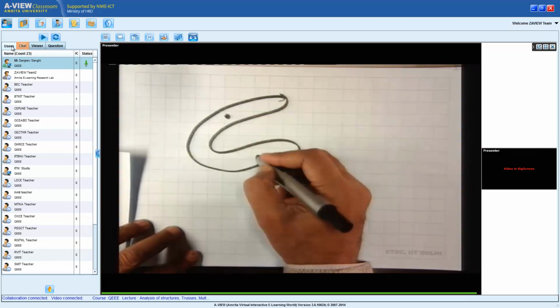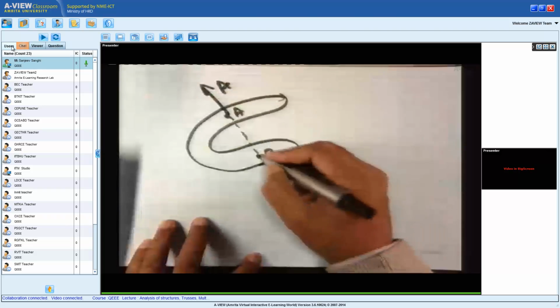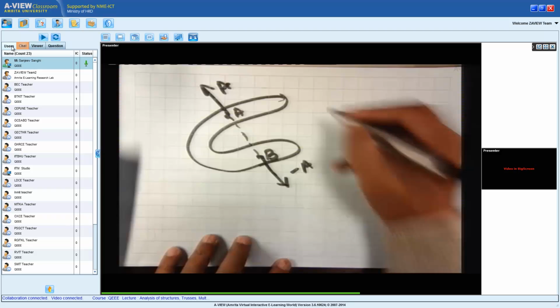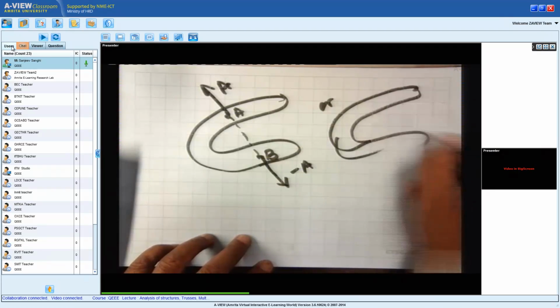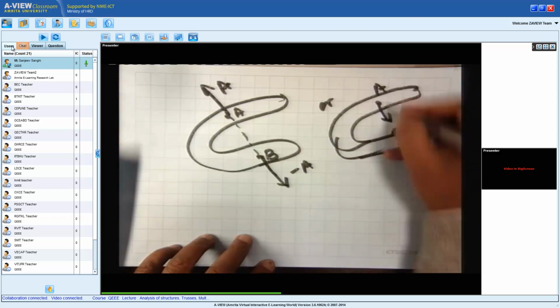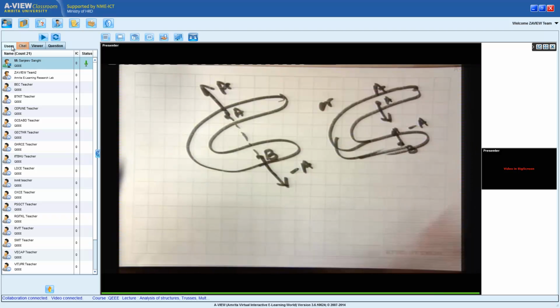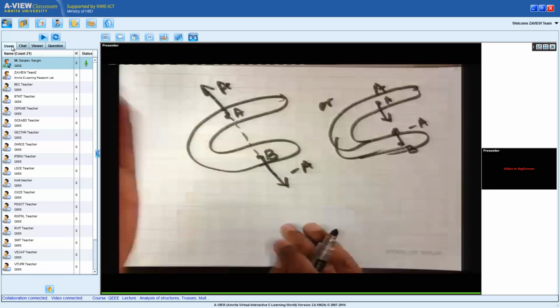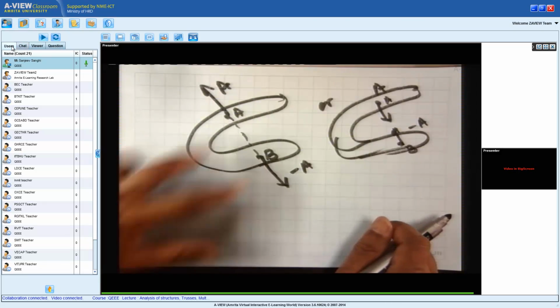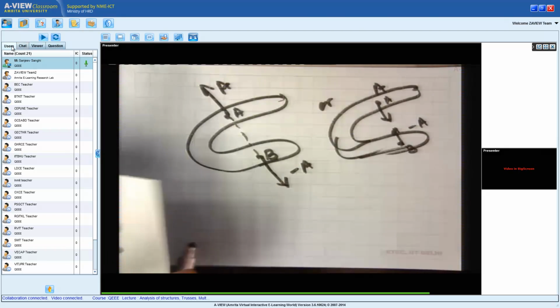And I'll just pictorially show this before I end. So if this was my original body, this was point A, point B, then the effective reaction, we will have a single force A here, and this will be minus A. So we join A and B, and this force has to act along this line. And so therefore, when you have a two force member, the equations of equilibrium of this are automatically implied if we draw a free body diagram showing only a single force with its line of action known to us as the line joining AB.